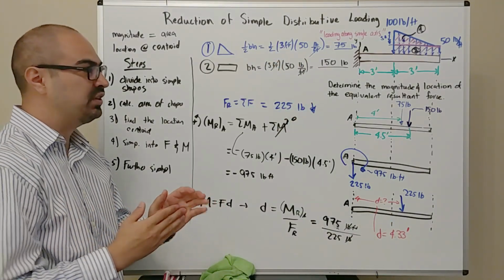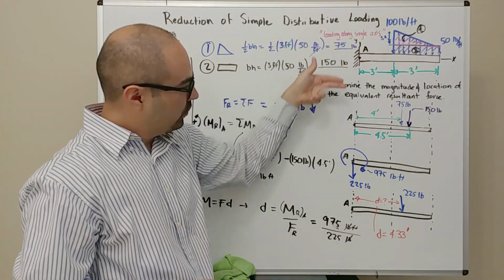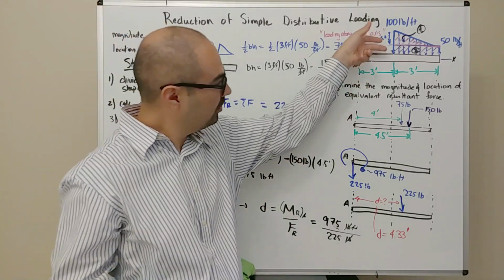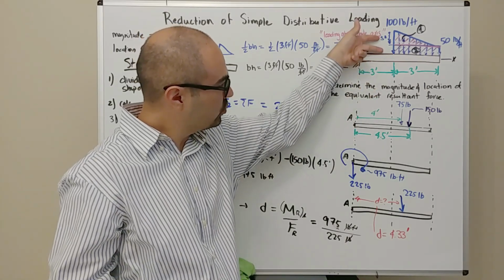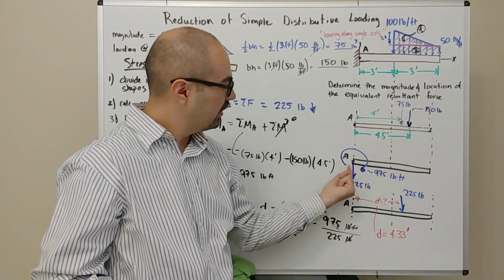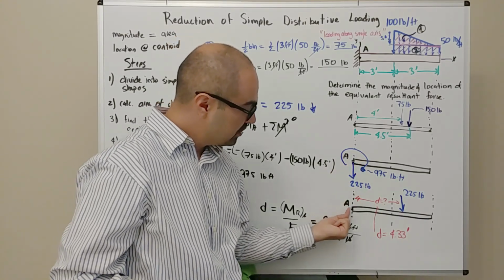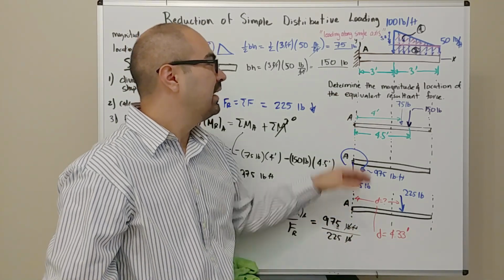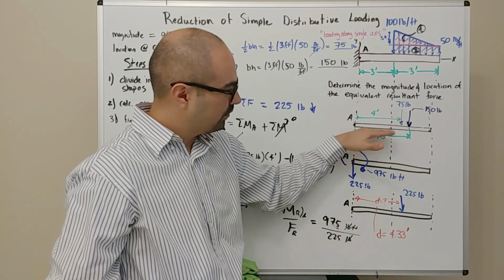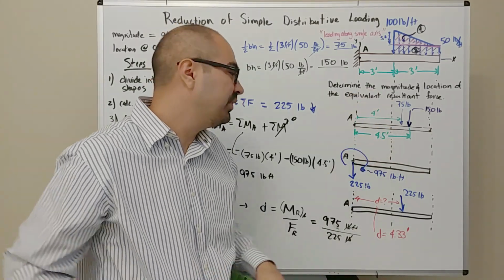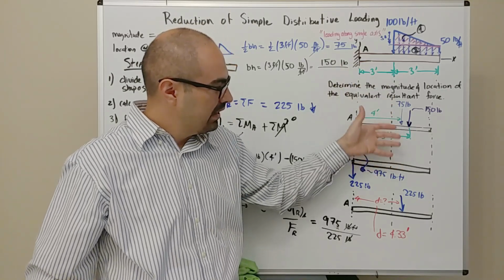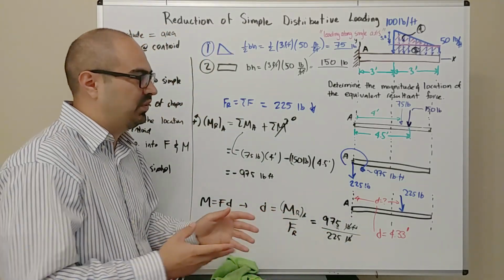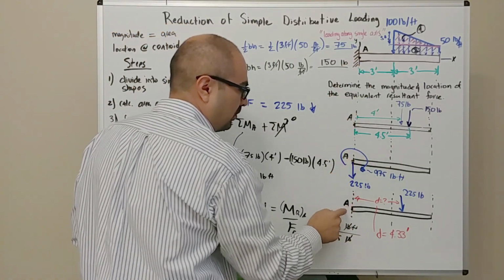Another important point to mention is that all of these free body diagrams are what we call equivalent force systems, although they don't look like it. There's a distributed load, two point loads, a single resultant and a couple moment, or just a force at some distance from a point. Although they don't look similar, if we model this beam as a rigid body like we do in statics, they all have the same effects on the body. They produce the same thing, and so we call them equivalent force systems. All of this, 1, 2, 3, 4.